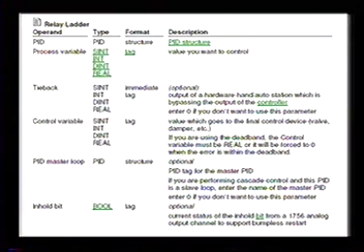But some people like a bumpless type control. I rarely ever do that, because if you put anything in manual, in my mind, I do such localized or process dependent offshore skids that anything in manual messes up the entire process, and you've got to shut the whole system down. So anything that goes into manual, I just shut it all down, especially a PID that's controlling a flow or something like that. You don't want to have that in manual mode. But some people want to go from manual to auto bumpless, and so they'll use these tieback values.